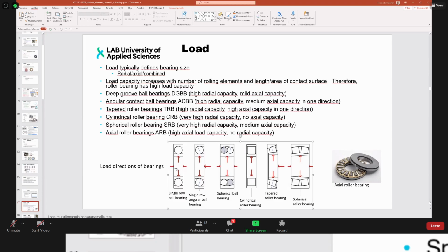So the deflection is increasing the load on the bearing. Whereas in the spherical ball bearing, if the shaft is deflecting, it basically doesn't increase the load on the bearing itself. So that is one extremely good property of a spherical ball bearing.